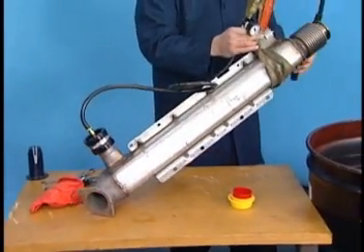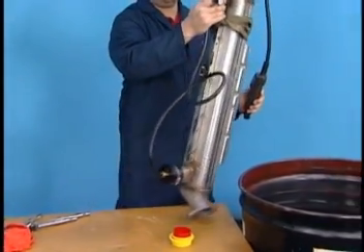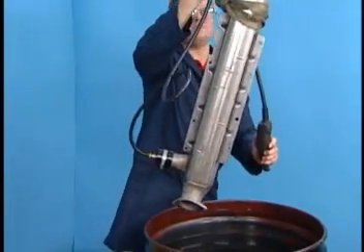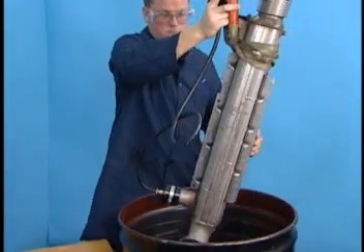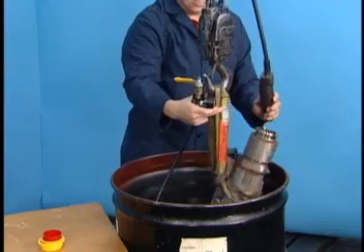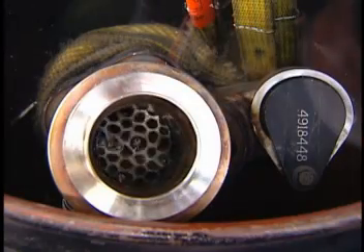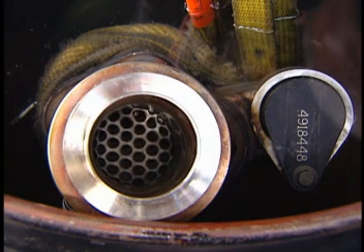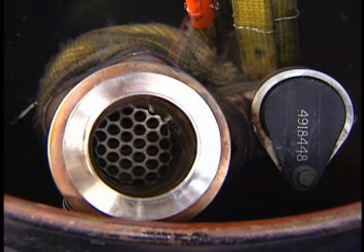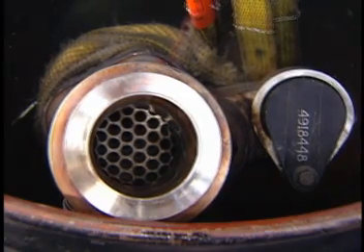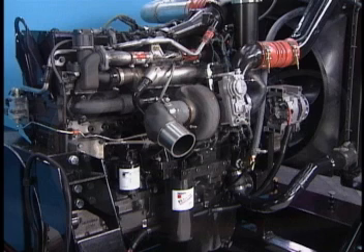Submerge the assembly in water in a vertical position and check for air bubbles. Inspect for bubbles escaping from uncapped gas ports of the EGR cooler or from the exterior shell of the cooler. Verify that bubbles are not a result of loose fittings or trapped air. Bubbles coming from a failed EGR cooler may be very small and/or may not be a steady stream. If bubbles are not observed, the EGR cooler is reusable. If the EGR cooler is not reusable, inspect the turbocharger turbine housing for any signs of coolant deposits.